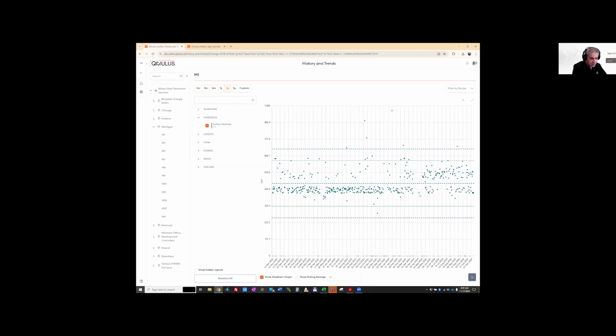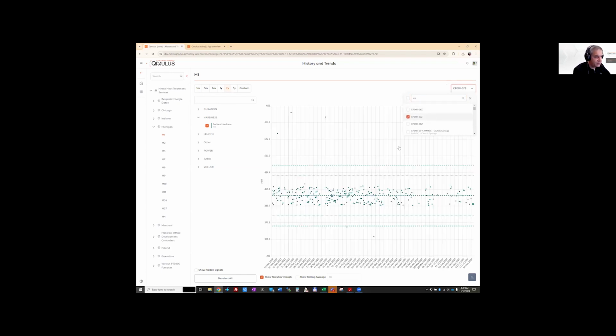So in the last 2 years in this example, these are all the distribution of surface hardness of this particular furnace, right? And as I could see here, this one had a surface hardness of 423 Vickers in 2024, load number X. And then this one was a different recipe. So here are all the white layers, case steps. But if I sort by this recipe, now this is only this recipe. Filter everything else out. These are all the hardnesses. And now you see here I have an anomaly, here I have an anomaly.